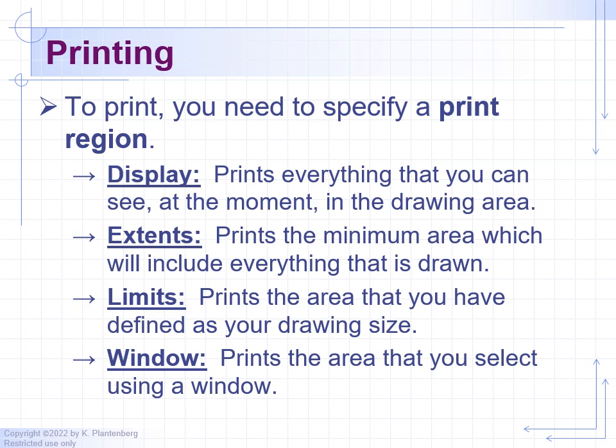So you can do it as the display. Display is going to print everything that's in the drawing area. Right? That's fine, but oftentimes it may not be lined up very well. And especially if there's a lot of empty space around your drawing, all that empty space is going to show up in the drawing. And that's not really what we want. We want our drawing to be pretty well centered, and we want it to take up around 2/3 of the drawing area. So display oftentimes doesn't work so well.